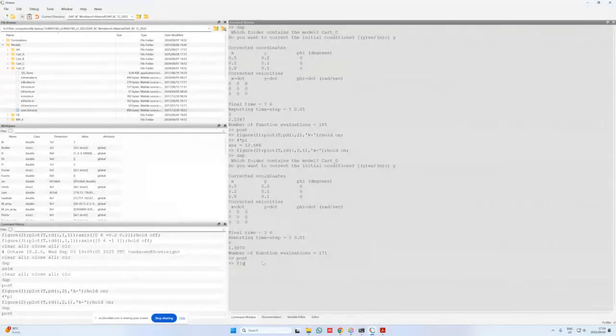Okay, so to do that, I'm now just going to type in fig U in this case. If I hit the up arrow, I can cycle through the previous commands that I entered, which had similar starting commands in this case, or starting letters, characters in this case. So the case that I'm interested in is now figure 1. So I'm going to use this. Now I'm still going to use the same plot. I just want to change now so that I'm working with a red dashed line. And if I'm happy with that, I'm just going to say hold off at the end.